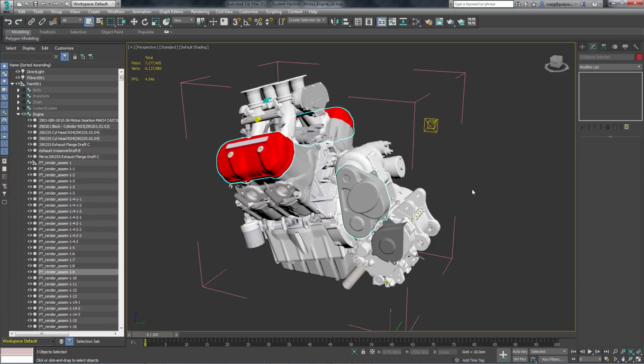Now, the reason why I'm mentioning this is that there are some considerations here. There's a lot of data here. In the scene, we have thousands of parts. So the data can get quite large, but that's not necessarily a huge deal for Unreal Engine to deal with. But if we need to do some fixes, maybe you need to repair the geometry, address the decimation on the geometry, or fix a UV map, for example, and you need one part to come back. If you've sent everything as one giant FBX file and you need to fix one part, you could get into issues back and forth with things like losing the positional data on an FBX file. And of course, exporting everything one by one can be quite time consuming as well.